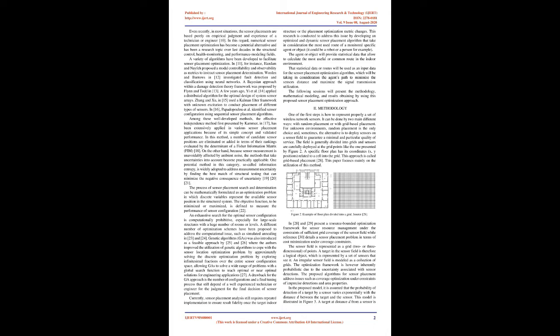A geometric algorithm based on trilateration is performed to estimate the position of an unknown point based on 3 other known points. Different techniques are used to calculate accurately the distance between the points, like time of arrival, TOA, time difference of arrival, TDOA, round-trip time of flight, RTOF, or RSSI 7, 8. Another important point that also depends on the positioning system's accuracy is the tracing of a global and local path planning to be used by a robot or mobile platform to reach its destination point. Path planning represents an algorithm for autonomous systems that lets robots find the shortest or optimal path between 2 points.